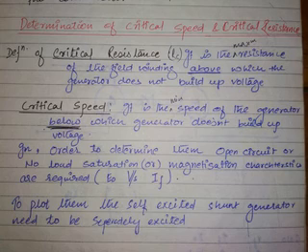This flux is added with the residual flux and produces more voltage. This more voltage will produce more current again, so the current increases, and this current again produces more voltage. Like that, the current keeps increasing. Within how much time? Maximum 5 or 10 seconds. So when you start a shunt generator, within 10 seconds the voltage build-up takes place, gets saturated, and is readily available.